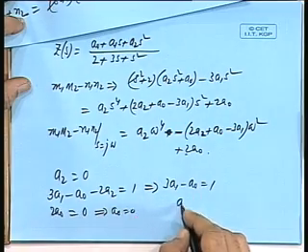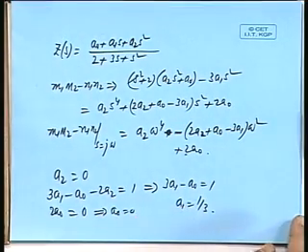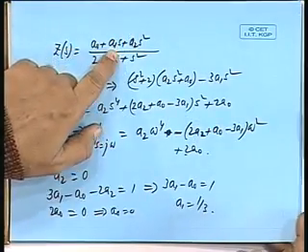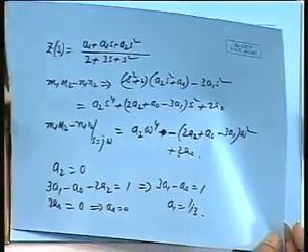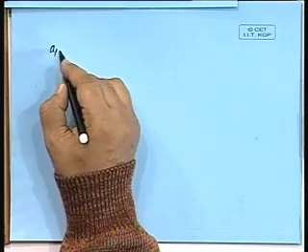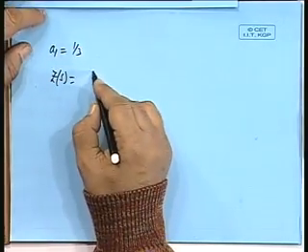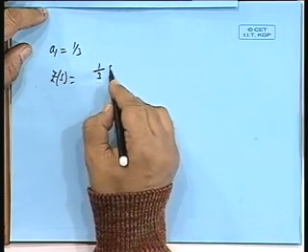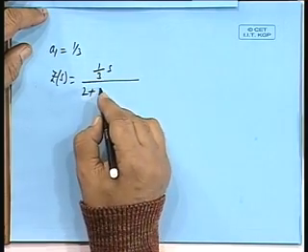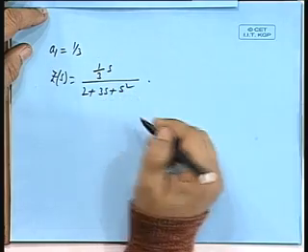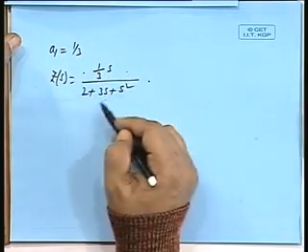So what does it mean? a1 is 1/3, okay, a1 is 1/3. It's very interesting, only one of them is present. Now let us see what kind of function it is. a1 is equal to 1/3, so Zs is 1/3 s divided by 2 plus 3s plus s squared. Can you realize it? Is it a realizable function? There is nothing here, nothing there, only one term, and here it is a quadratic.